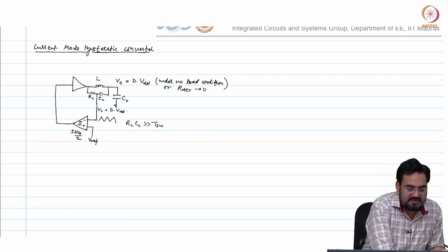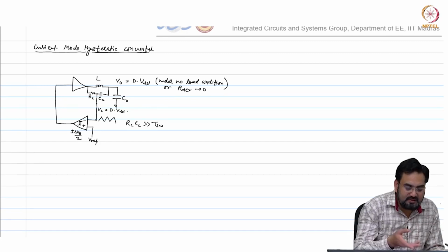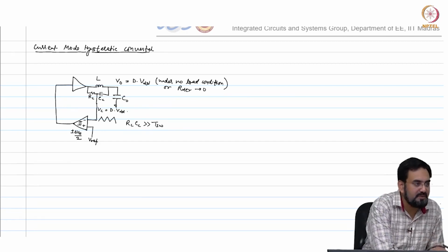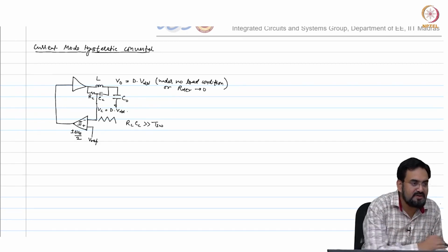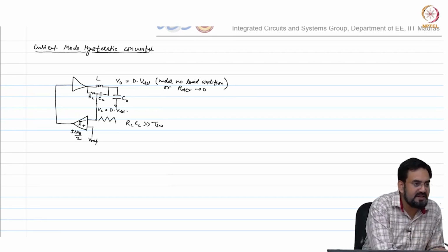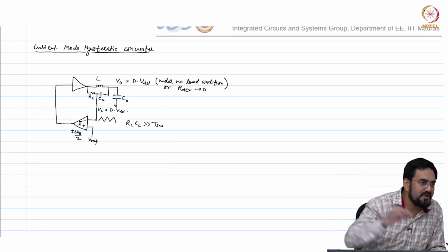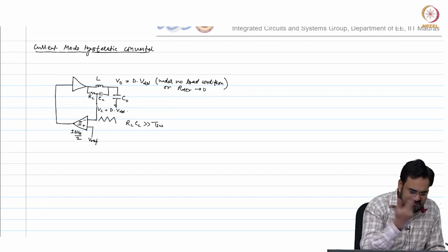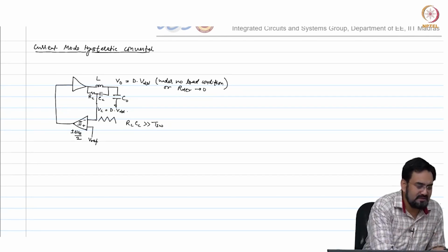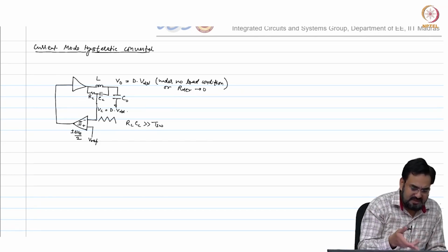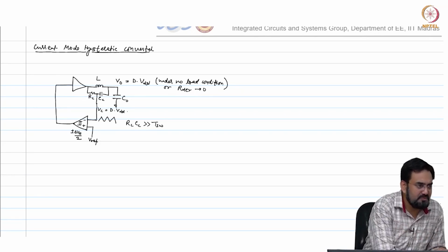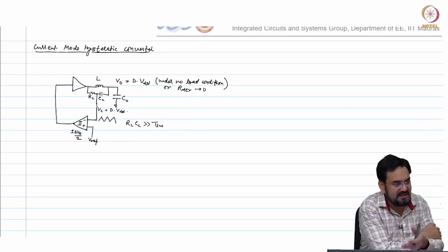What about the transient response? And the other thing, good thing, is now you are not depending on output ripple. The hysteretic window we were keeping was based on the output ripple required. Now I can keep this 50 millivolt or 100 millivolt, and it will not affect your output ripple, correct. Output ripple will always depend on switching frequency and this LC filter.